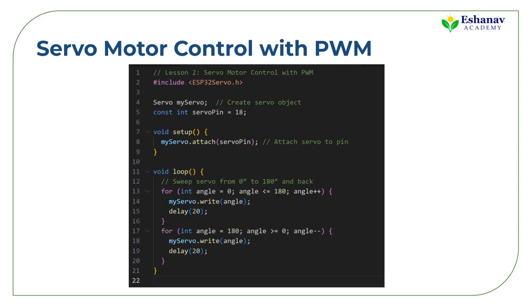On the ESP32, libraries like ESP32 Servo handle these timings for you. But it helps to understand the physics. The motor's internal circuit is literally measuring pulse widths. When powering a servo, always consider its appetite for current. Hooking it straight to the ESP32's 5V pin is a rookie mistake that leads to resets and jitter. Use an external supply and tie the grounds together.